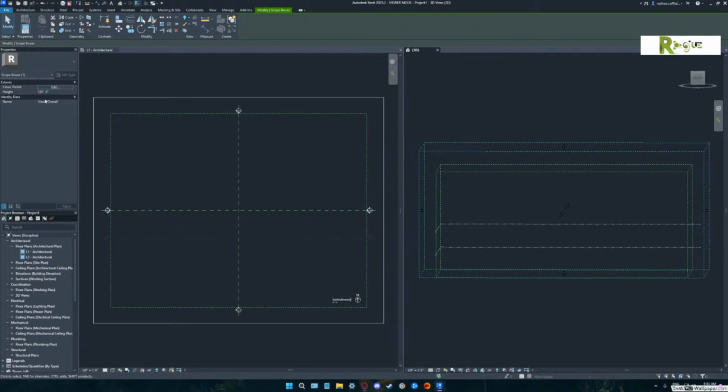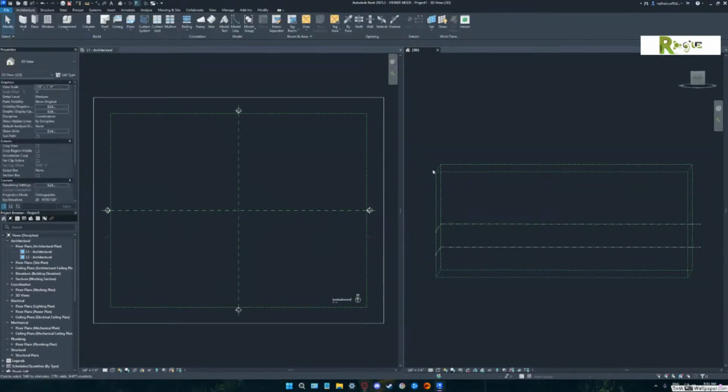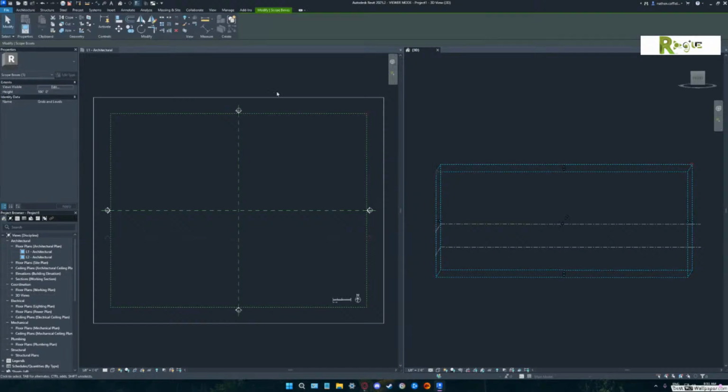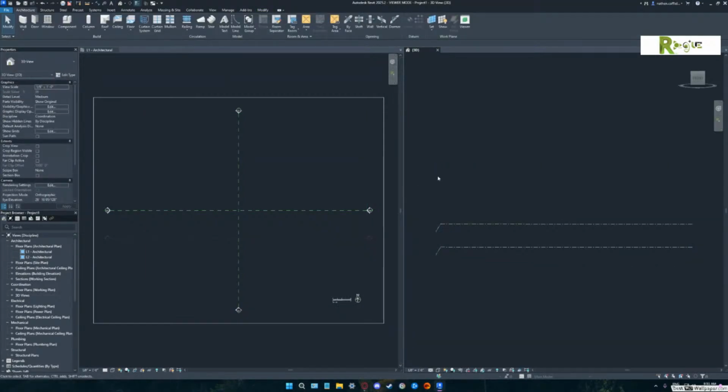I'll be honest with you. I'm not keen on scope boxes. I'd go ahead and delete that. Both of them. And if you pick that one, you're going to see that as well is another scope box, and you can delete that one as well. And how are you deleting? You're clicking a button on the screen or on your keyboard. There's a delete key that works the same.